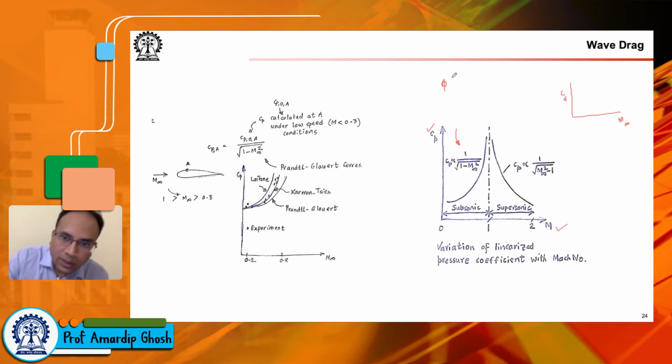However, in this particular diagram, what you see is based on the velocity potential formulation for irrotational but compressible flow field. Okay, because remember, wave drag, your shock waves are a compressible flow phenomena. So here we are flying at large enough Mach numbers where shock waves are happening. So in this case, the velocity potential formulation based on which we get this plot is applied to irrotational compressible flow fields. Okay, and then there is something called the small perturbation approach or linearization. You will hear these words.